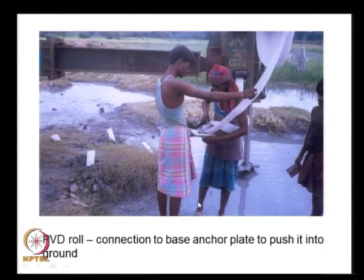And here we see an example of the PVD that is coming in a roll. This PVD is being connected to an anchor plate that is connected to this rod, and it just simply pushes the anchor plate, and along with the anchor plate the PVD enters the ground. And here we can see some PVDs that are already installed, and the entire field is a soft clay soil.